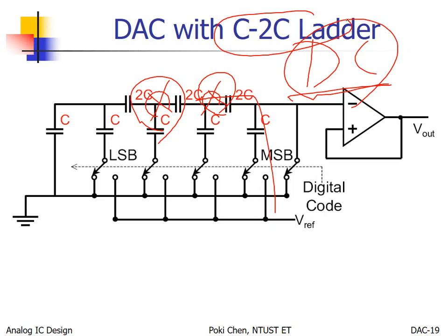Sorry for that. But you will say, hey, we have R-2R. Oh, congratulations. If all those are resistances, no worries. Why? Because a resistor will provide such a DC path for you to dissipate all the error and noise here. So we have R-2R in practice, but we don't have C-2C in practice. Only in idea. You can talk about this only for fun, but don't do it.